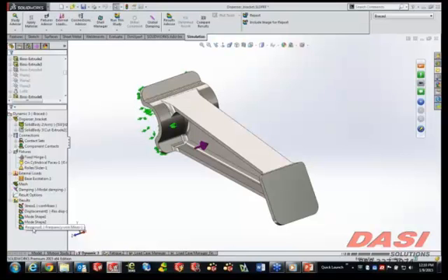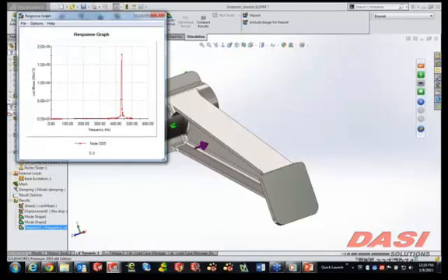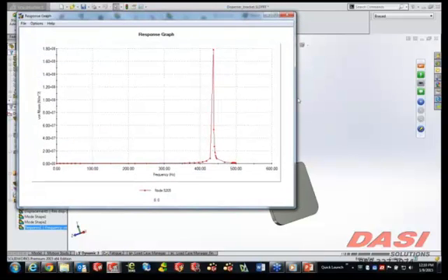And all along with dynamic simulations, we've been looking at these things called frequency response graphs. Now, this frequency response graph tells me very little, tells me some, but very little. Tells me that the magnitude, the highest part that we had here, happened to be around 436 hertz with our frequency. But other than that, the rest of this data is really kind of unusable.